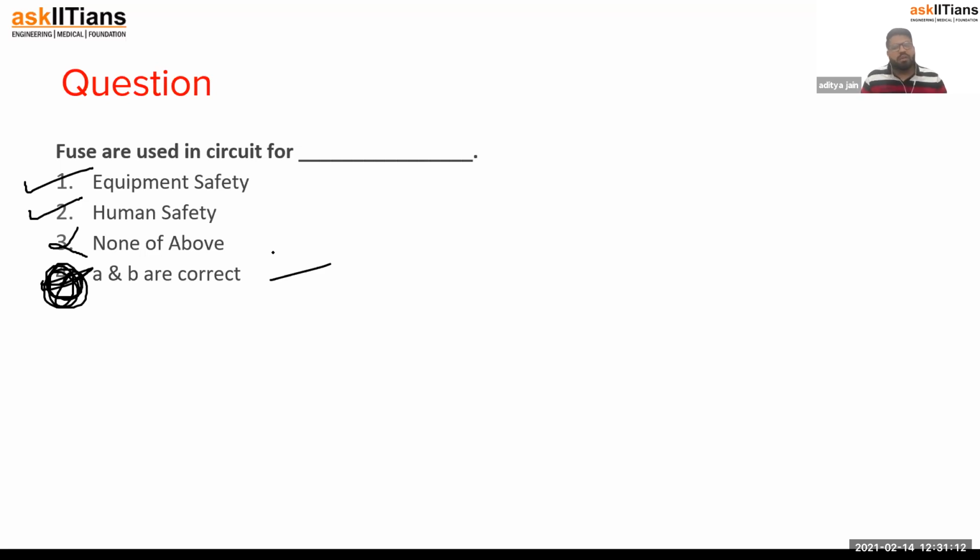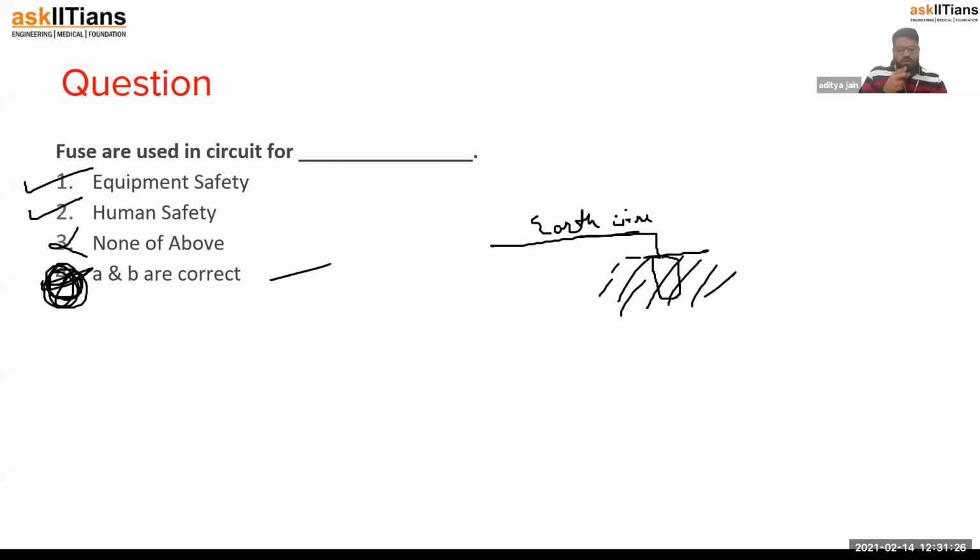So due to that metal plate, this process is known as grounding. Suppose this is the earth wire. This is connected to a metal plate, and the metal plate is buried deep inside the earth. So this is the grounding process or earthing process. Okay, this is the earth wire. So we have seen these are parallel combinations in domestic electric circuits. Potential difference in India is 220 volt between live wire and neutral wire. There are 2 different lines, one for high power rating devices and one for low power rating devices. So I hope everything is clear.